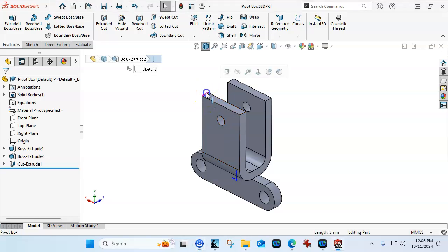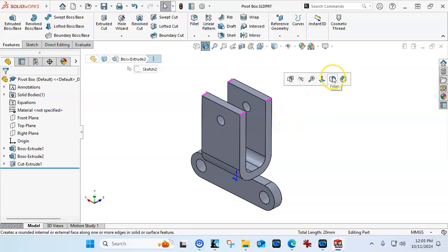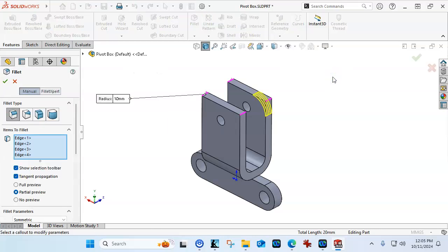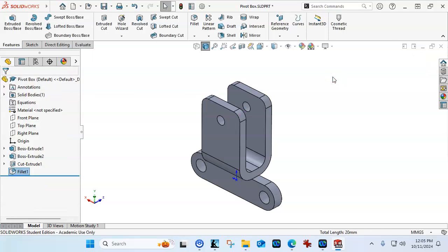I had a little bit of a blink on some notifications coming up, so I paused and went ahead and created my folder and my naming. So if I do the control select, probably one more control select, then I'm going to put in the radius of 5. And since I haven't moved the mouse button, I notice that I have the right mouse to complete, so I can hit the right mouse button and that will finish it.